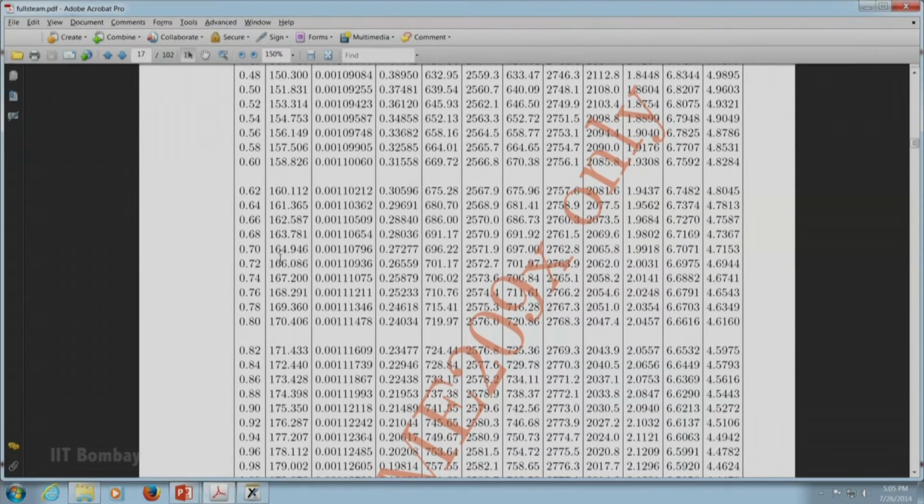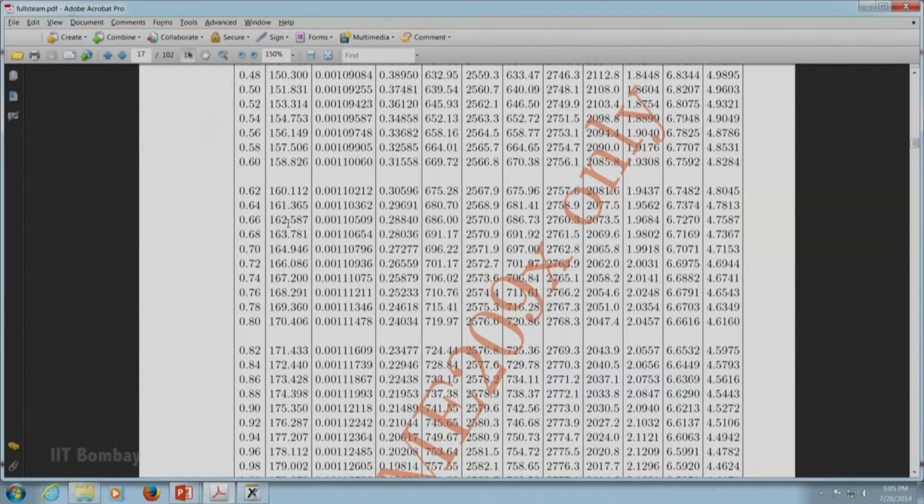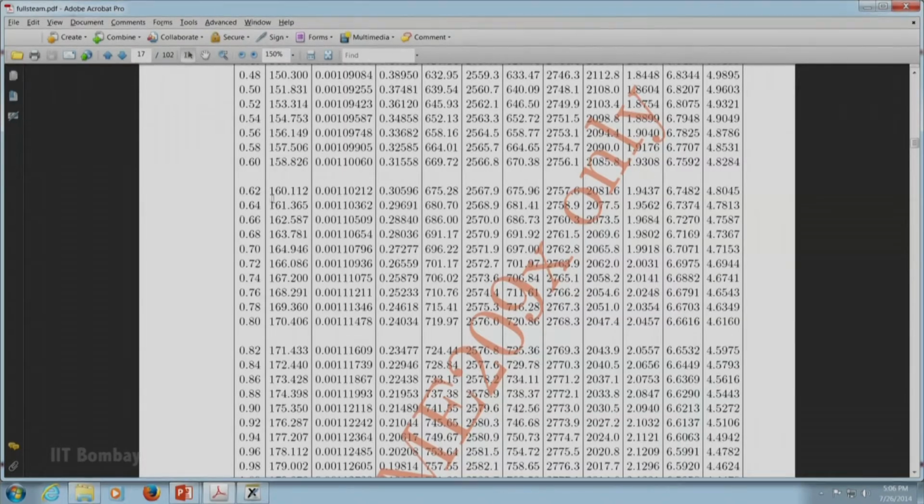The temperature happens to be around 163 and 164, and we know for sure that 550 degree centigrade is much more than this. It implies that we are in a superheated region straight away. A very simple calculation can be done here. Our temperature is 550 degree centigrade, which implies that we are in a superheated region straight away. So, knowing that point 1 has an x value, it is a two phase mixture, while point 2 is in the superheated region, by understanding its temperature and pressure. With this knowledge, let us come back to solving this problem.